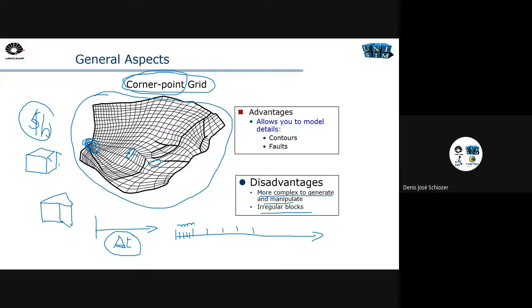and the corner point is much better, and I just use the corner point because it is much better to represent the reservoir. It has some numerical aspects and time aspects that, in general, are good, but you have to be careful because sometimes the Cartesian grid is faster, so I can use a finer grid with behavior similar to these corner point aspects, okay?